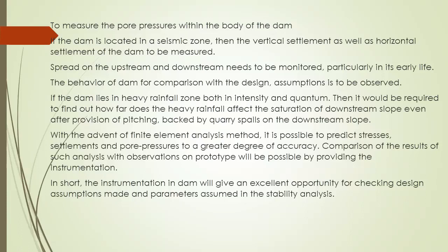The behavior of the dam for comparison with the design assumptions is to be observed. If the dam lies in a heavy rainfall zone, both in intensity and quantum, then it would be required to find out how far the heavy rainfall affects the saturation of the downstream slope, even after provision of pitching, backed by quarry spalls on the downstream slope.